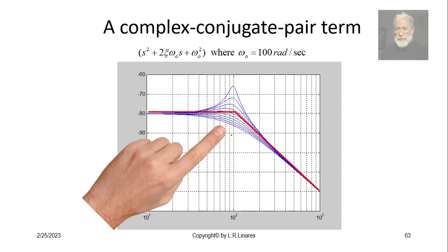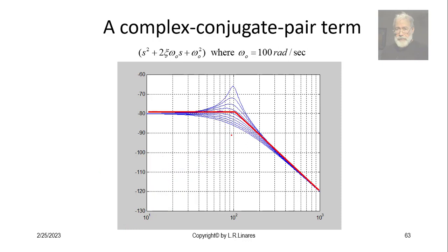That gave Butterworth possibly the idea of combining some parallel poles with positive overshoot with some other poles with negative overshoot, so that they would cancel the overshoot near the corner and have a much smoother response for the filter. That was genius, all right? So all the poles contribute with the same corner, so they have to have the same omega naught. They have to be at the same distance from the origin, but they will have different damping factors.